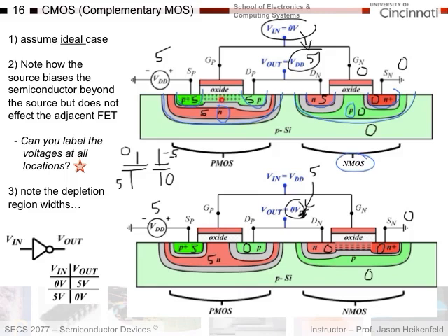So again, I can't emphasize enough how beautiful it is that a semiconductor system works so well that you can make a device so simply, integrate complementary metal oxide logic. And the thing I love about this is the thing I said at the beginning of the course. This whole course is based on p-n junctions. And you can see it here. You can see that an inverter is heavily dependent on p-n junctions, especially if it's going to latch between logic states and not have any net current flow to hold the logic state, which is what I want. I want a low power microprocessor.